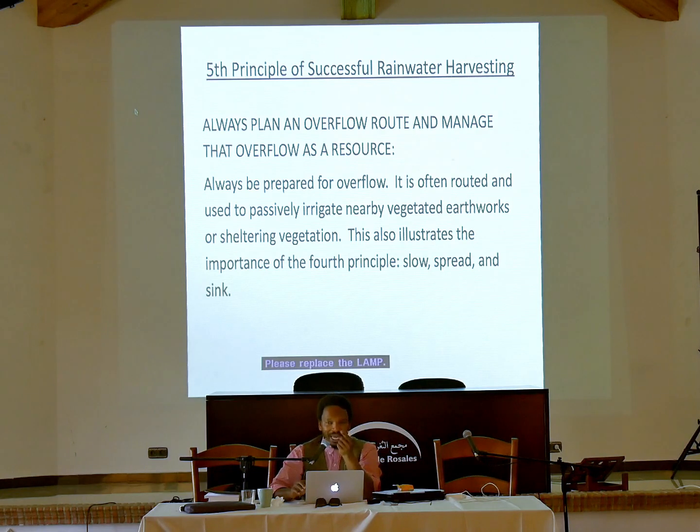If you have water overtake the wall of the dam, that's another no-no, because if you get enough water flowing over the dam for long enough, the dam fails. The wall fails. Or if the dam wall isn't built properly and you have water start to seep through, the wall fails. So being able to manage the excess is often a key to the long-term success and the long-term viability of whatever means of storage you have in mind.